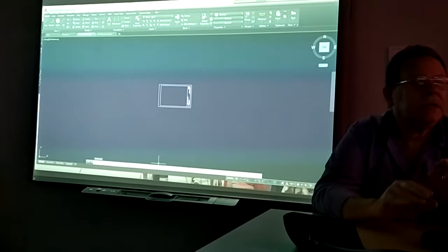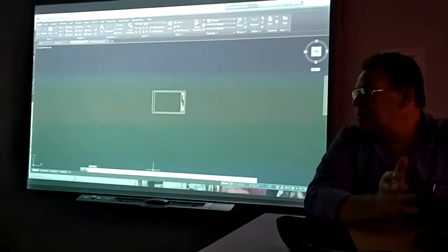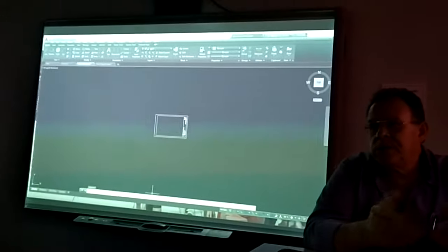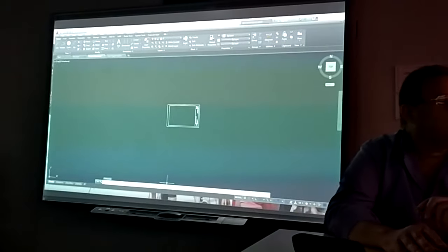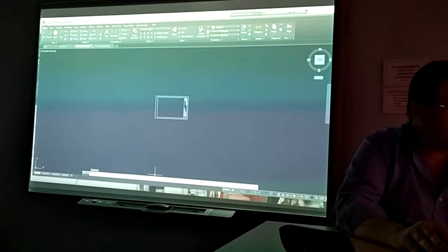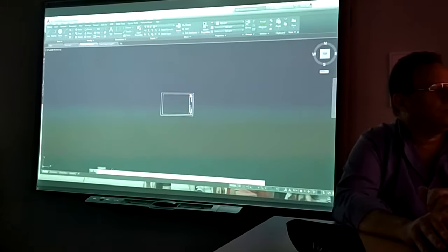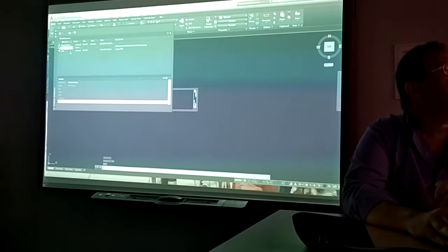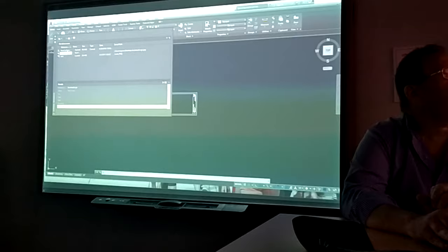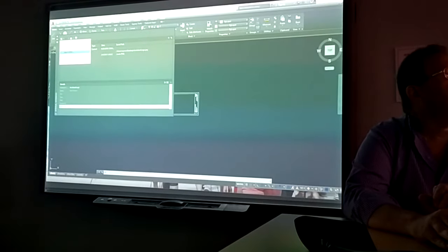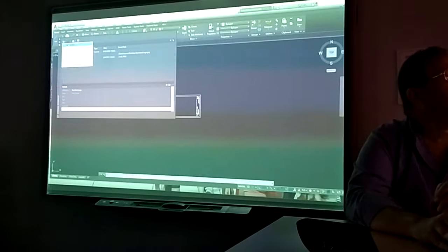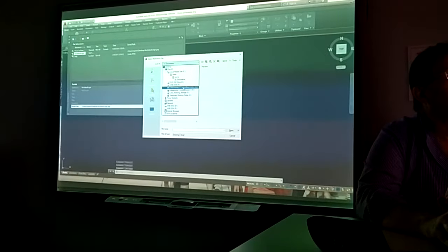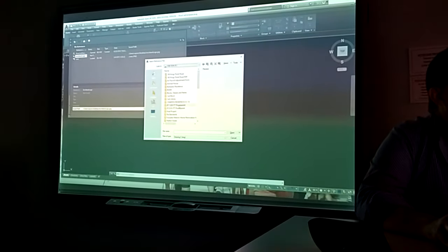The reason why we do it, we call those drawings bases, the base plan. In the base plan, we don't put lighting, we don't put dimensions, we don't put text. We just put the plan. So if you type in XR, X reference. You could bring in by pulling down this menu here, attach DWG, look it up, where is this is